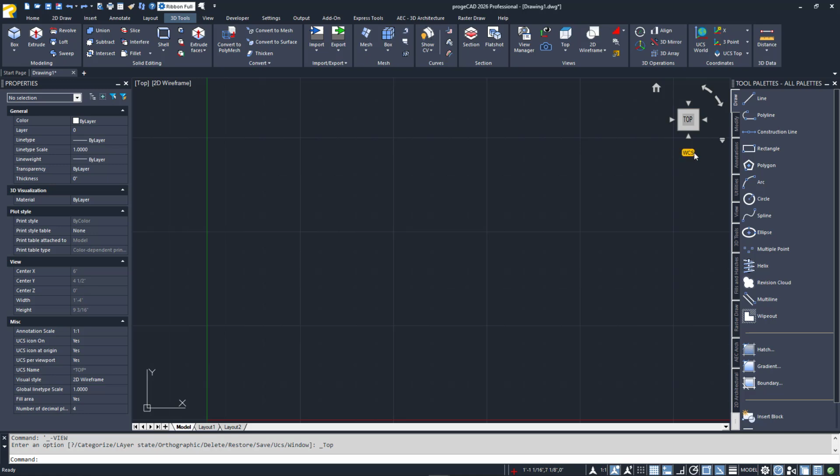The icon at the bottom that reads WCS allows quick access to any custom user coordinate systems you may have, or the orthographic projections as we saw in the viewport tools. The two curved arrows will rotate your view 90 degrees from the current Z-axis. And finally, in the middle, the cube has arrows around the edges which provide quick access to the back, front, and sides. When you click on the main tile of each side, you'll go right to that view. Finally, each corner of the cube is a shortcut to view your model in the corresponding isometric projection.